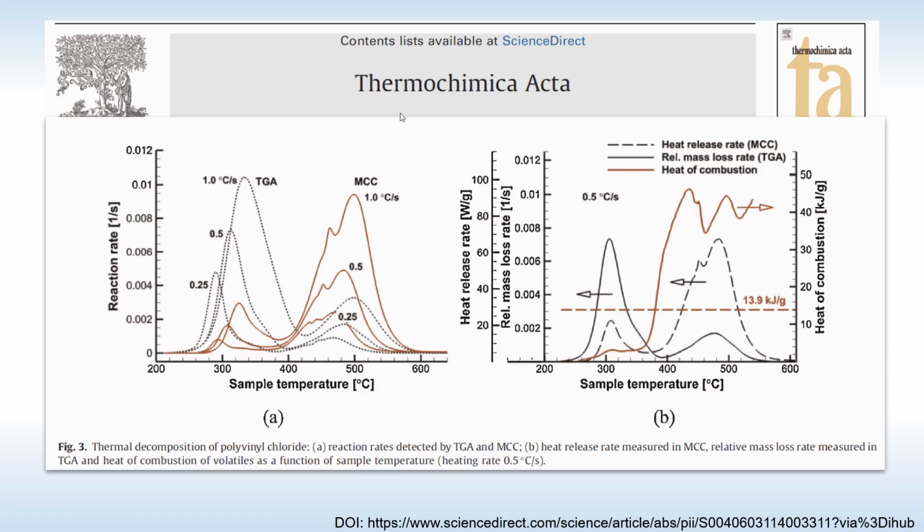The goal is to emphasize that if you are interested in reproducing the procedure I am going to present here, you may want to be careful and possibly not use the MCC data series as target directly. I believe that integrating the heat release rate should be fine and could be used as a constant heat of combustion. Also, many people assume the heat of combustion to be constant to begin with.